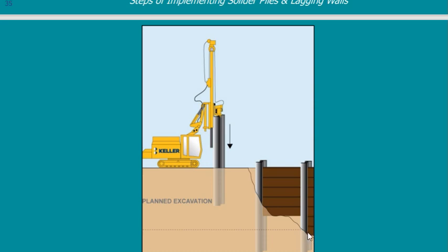I cannot do this with very soft soil. I cannot do this with sand, because if I do this with sand, it will just jump. It should be silty sand, clay sand, so that it can stand in place for 20 centimeters, 30 centimeters, anything that I can put the lagging.